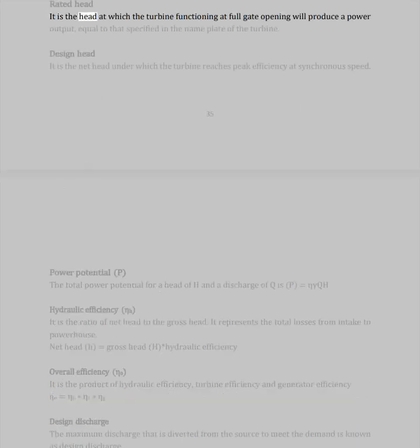Rated head is the head at which the turbine functioning at full gate opening will produce a power output equal to that specified in the nameplate of the turbine. Design head is the net head under which the turbine reaches peak efficiency at synchronous speed.